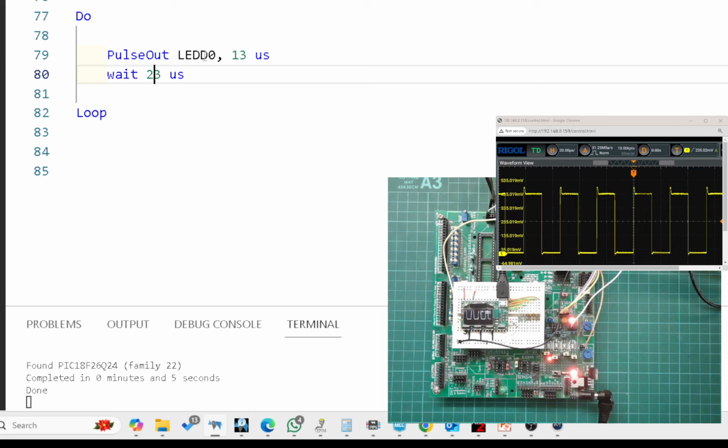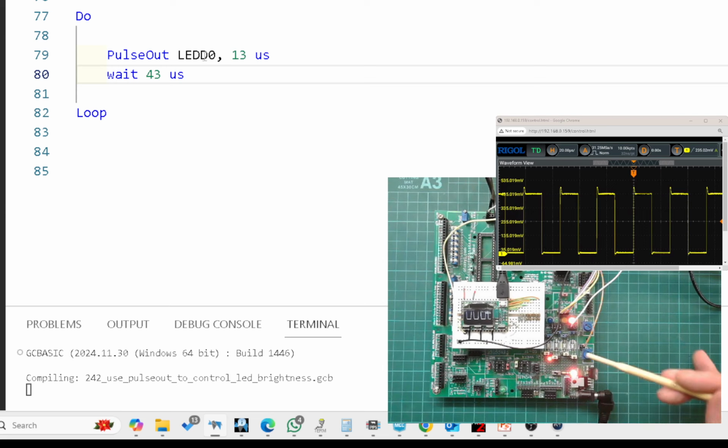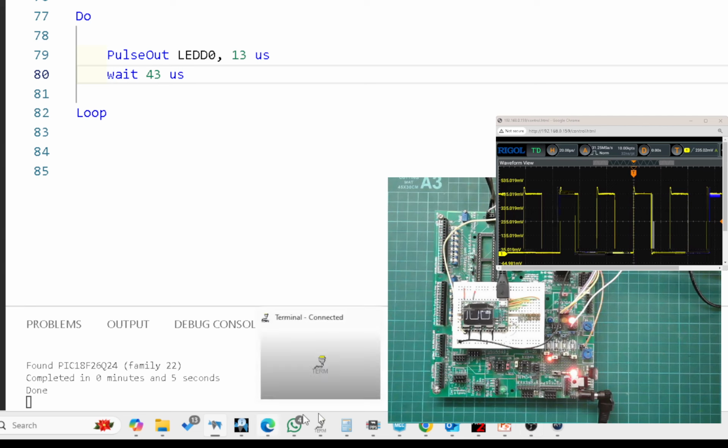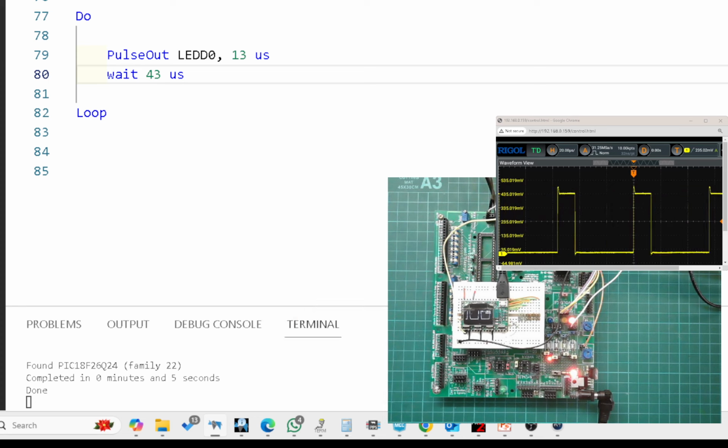Now you can see in the signal that's being put on the screen there, as I increase this value here, the shape is now on and off more, and the LED, by the way, accordingly is changing. And you'll see the shape change as I increase that time, but I maintain the on time. I'm changing the off time. Now, why isn't that scope updating properly? I'm just going to go out to the Rigol because I can see it on there it is. It's finally caught up.